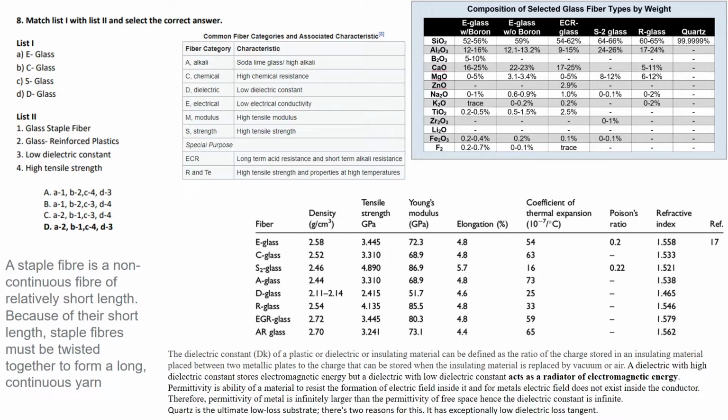a thermoplastic or thermosetting resin matrix medium in between. So you'll have that entire composite. You'll stretch from both the sides. Then if the composite is made out of S glass, which has highest tensile strength, then it will break at a higher point because its tensile strength is highest. And if the reinforcement material is made out of this S glass, then definitely the performance and the tensile strength of that medium would be highest.